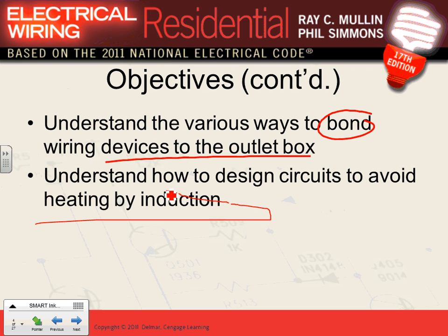Inductive heat. I can summarize it with one thing: if you have a circuit, you have to pull all the conductors of that particular circuit in the same conduit or cable. For example, I have a 3-phase circuit made of 3 phases, a neutral, and a ground. Can I put them in 5 conduits or 1 conduit? 1 conduit. The same for trenching: can you trench them in 2 different trenches, or do you have to group them together in 1 trench? Group them together.